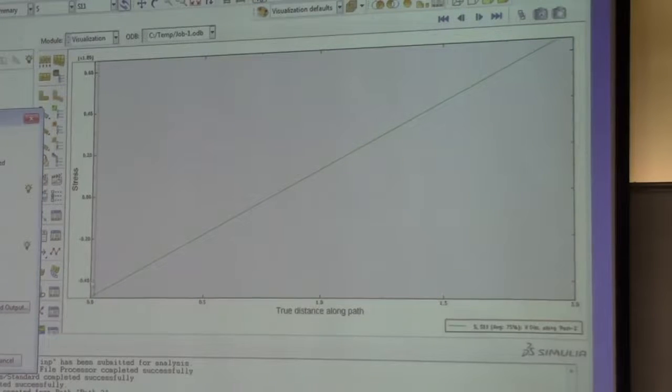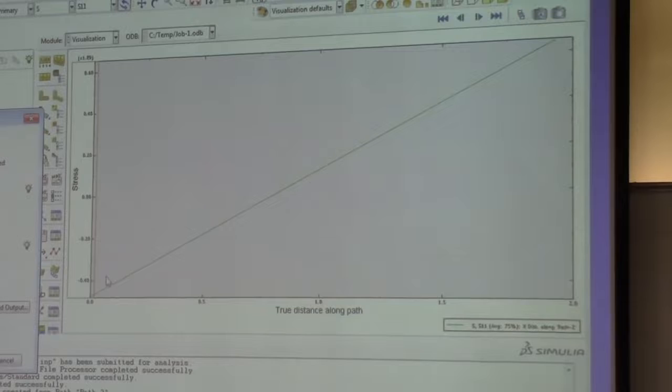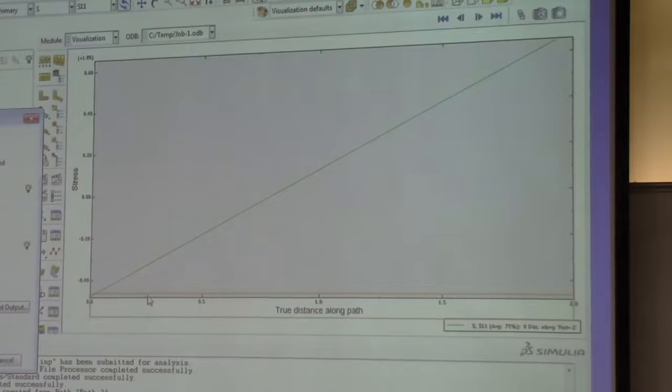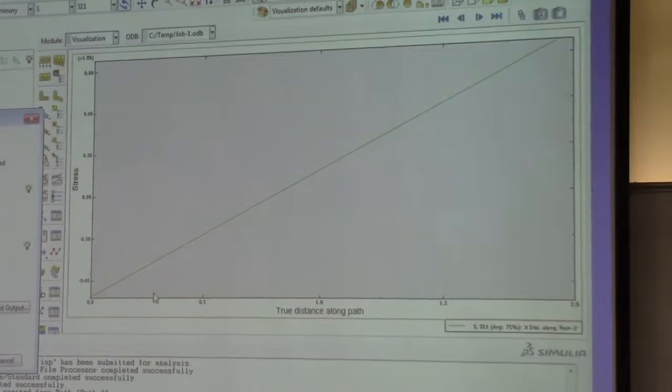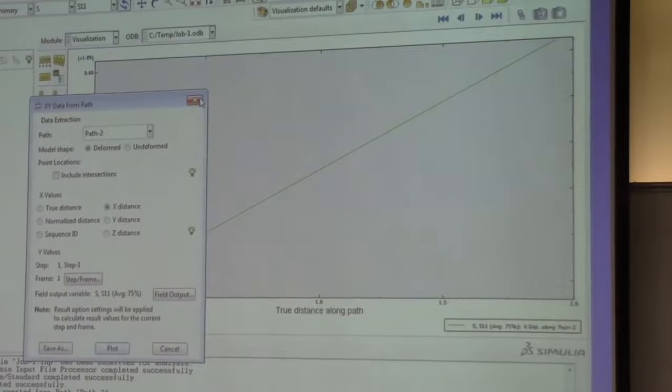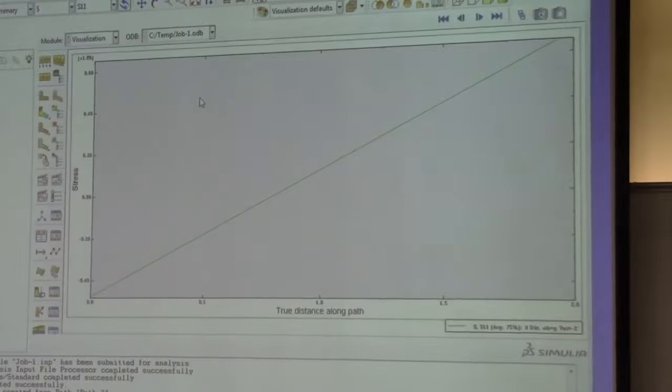So the true result should start from here and decrease, decrease, decrease, and then increase. So this should be the minimum result, right, around here. But if you only use one element, you will miss this minimum result and the result will not be accurate. That's why you need to use your background knowledge to determine how many elements is best for your problem.